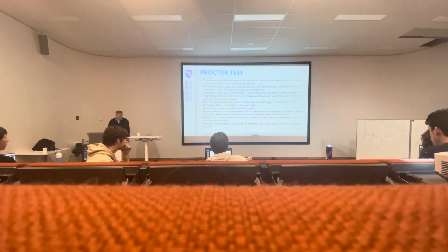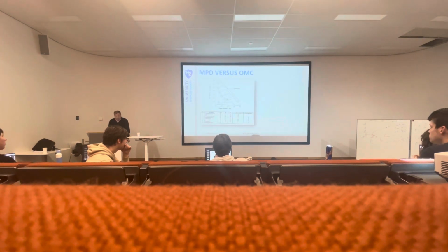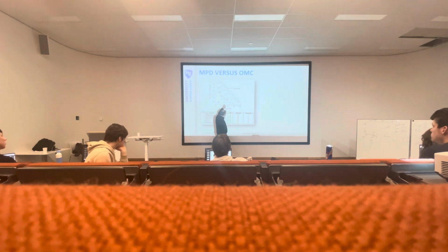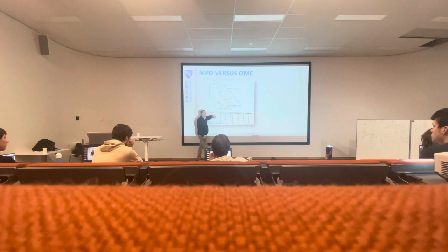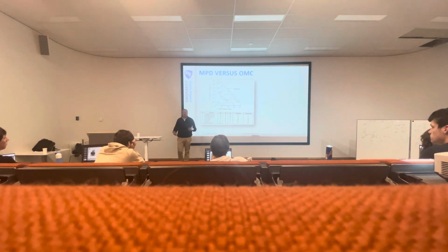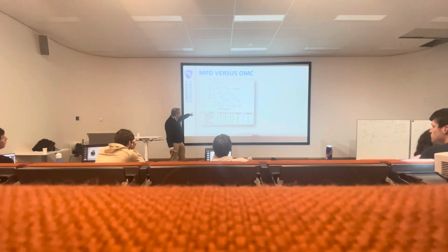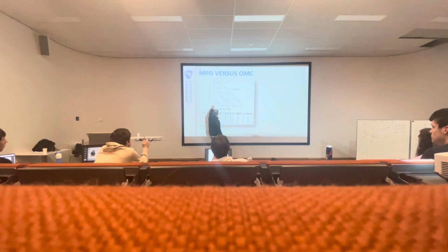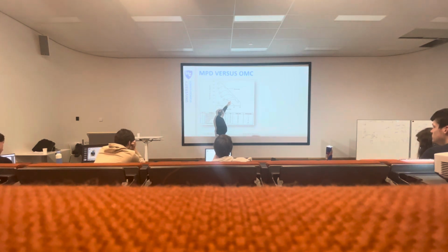So this you have to read one more time. Here you can see the clay soil, poor density. Not good soil. But you can see the water content: you can get more or less the same results between 10 up to 18%.